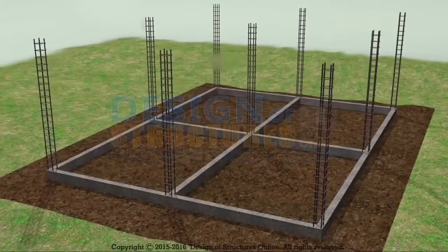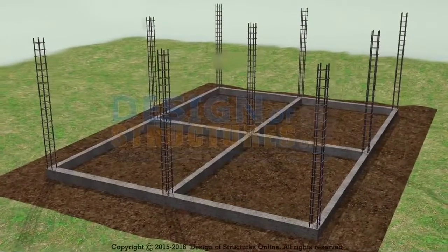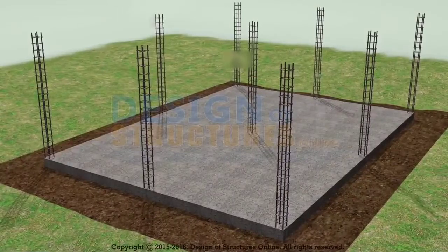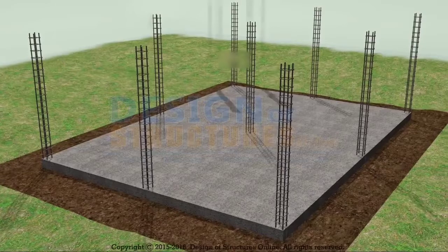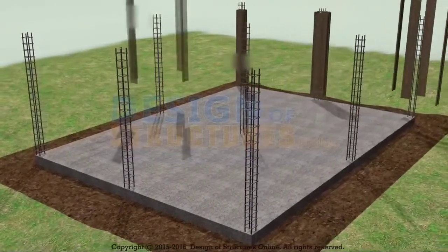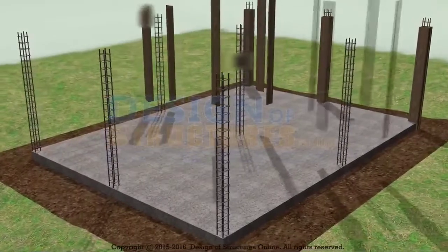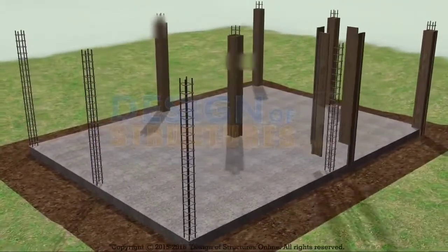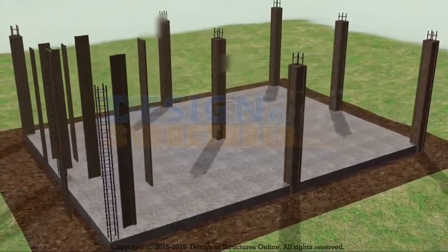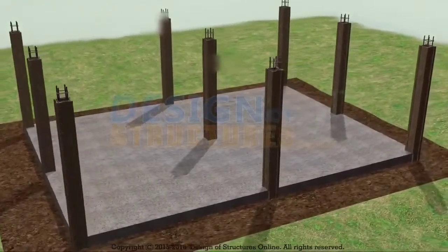Slab concreting. Grade slab requires no reinforcement as it is resting on ground strata itself. Top of plinth beams and grade slab should be at the same level. Column shuttering. Column shuttering should be rigidly constructed and efficiently propped and braced both horizontally and vertically, so as to retain its shape. The shuttering should be set accurately to the desired line and levels and should have a plane surface.